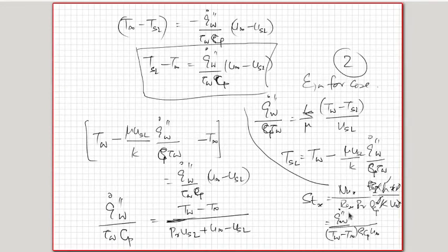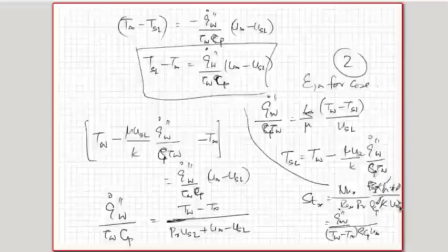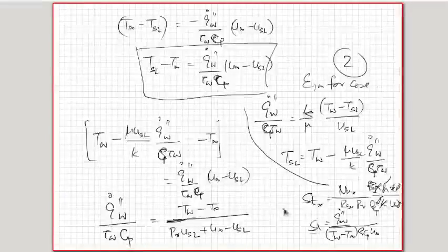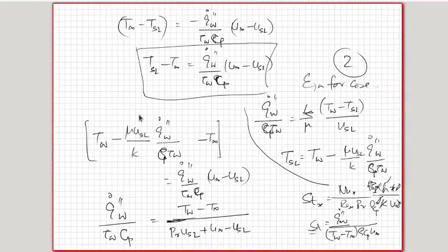So Q dot double prime divided by rho CP U infinity into T wall minus T infinity gives me Stanton number. So if I from this try to write the expression for Stanton number, then this T wall minus T infinity will go here. I'll multiply by rho, and this tau wall I'll write in terms of Cf by 2, and then we will simplify this.